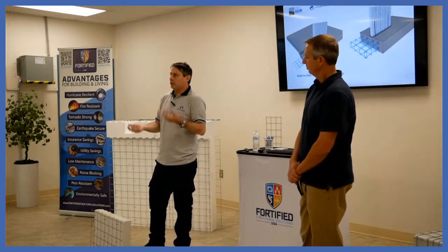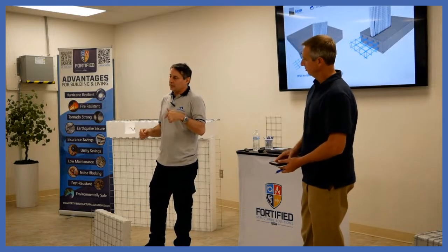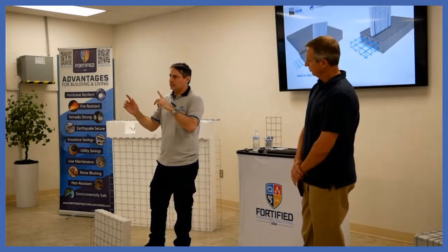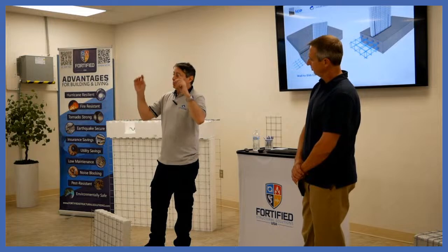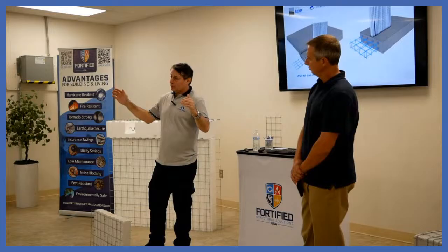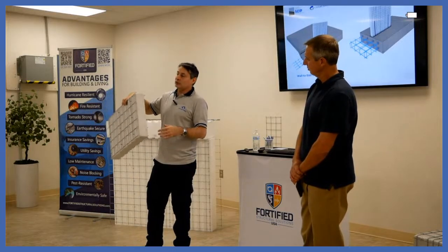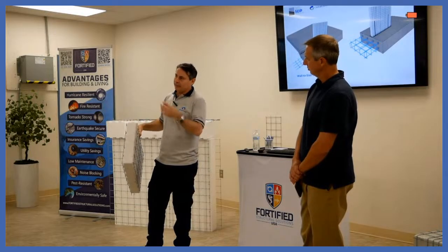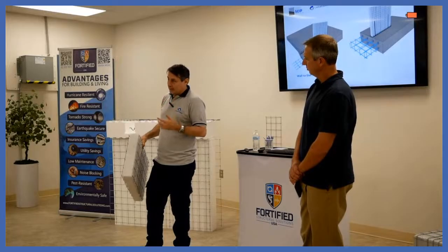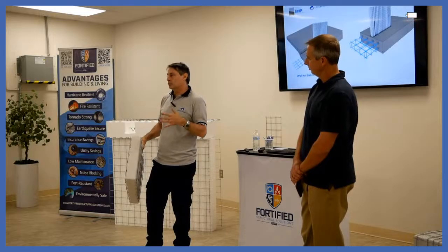When you make it out of concrete, it's about almost the same. What's the difference between them? Well, the skip will deflect a little bit more because the core is empty. The core is empty, so it's not as rigid as something that is 100% concrete. But the concrete has more weight. So it's a nice balance of both things.